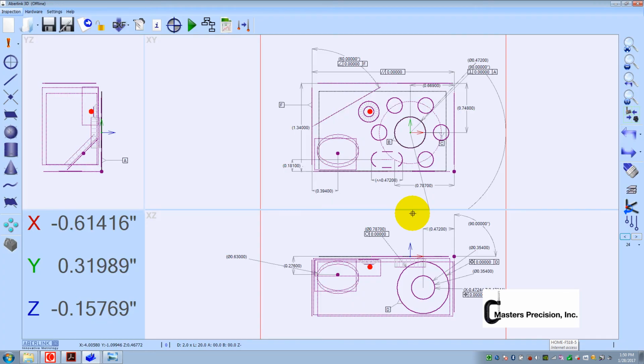So that was the angled plane here to the front plane here. And it got the back plane. You can see where it highlighted. So I'm just going to left click and say undo and try it again. I'll go that plane to that plane. There's the 45. So we'll bring it up here, left click.